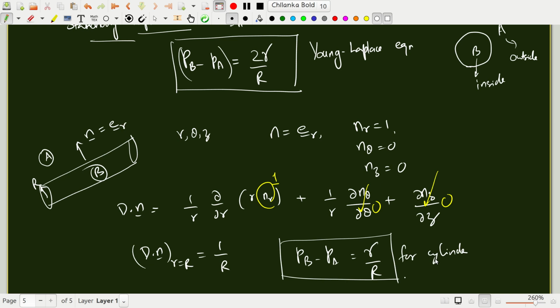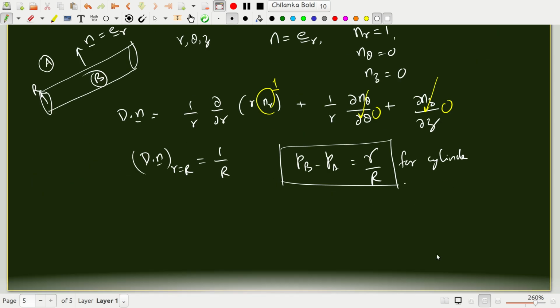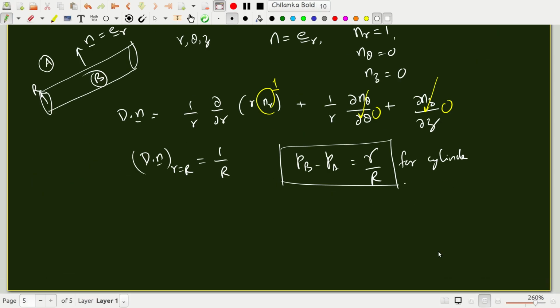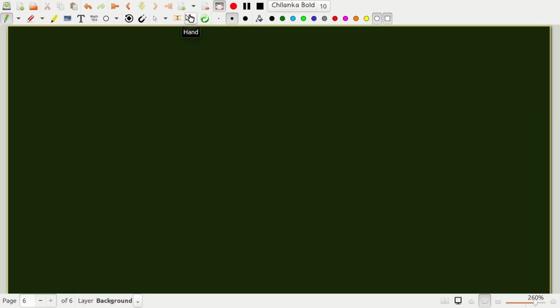Okay, so this is how one understands the idea of interfacial tension in the context of stationary fluids. Of course, this is going to play an important role even in hydrodynamic stability, as we'll see a bit later. Now, the tangential stress balance is obtained by taking the dot product with, for simplicity, I'm going to assume that it's a two-dimensional interface, because otherwise there are two tangents, as I've told you.